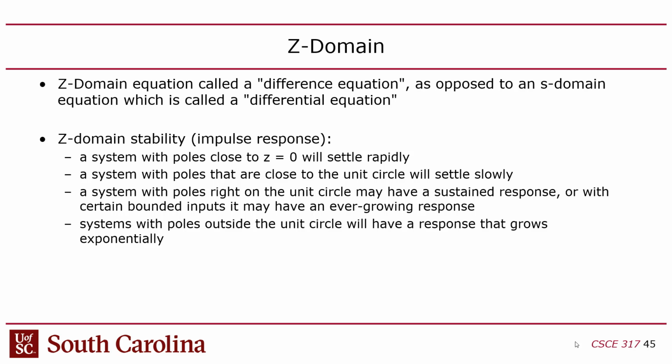The biggest problem with Z-domain is that no one really knows what the, well, I shouldn't say that. It's not that no one knows, but the stability criteria is a little vague. So with S-domain, it's very simple. If the poles of your S-domain transfer function are in the left plane, meaning have a negative real value, stable.